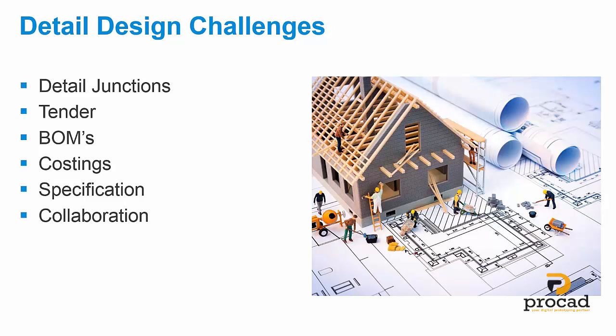So some of the challenges we might see are tricky detail junctions of where a roof might meet a wall, or it could be a detail of a head height going through a stairs that can get missed, and I've missed them myself in projects, and that are then discovered on site, and then some sort of remedial works have to occur, and work has to be undone, and it's additional cost either to the client or even to the contractor as well. And then we also have the production of tender information as well.